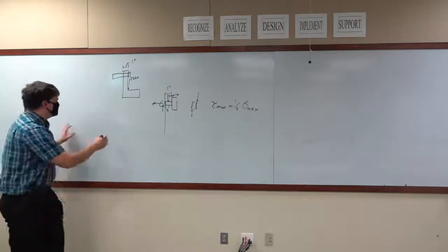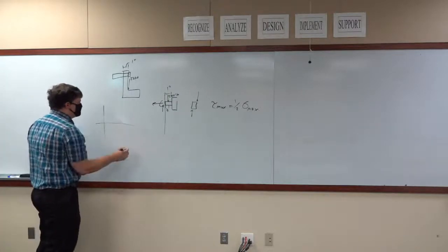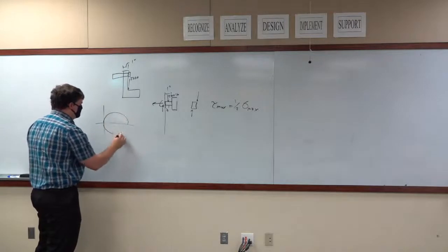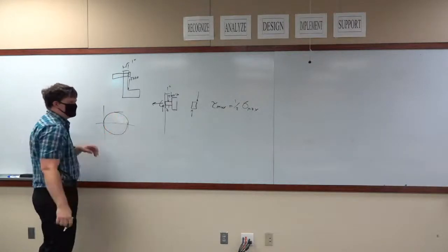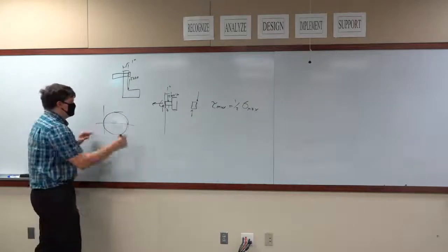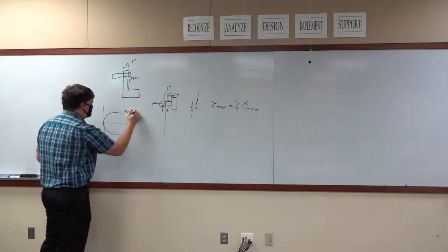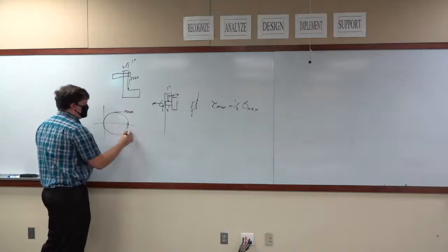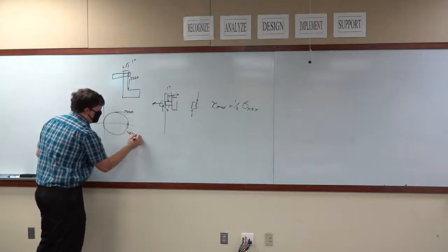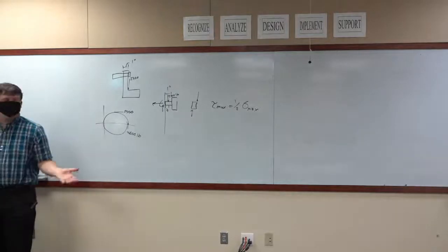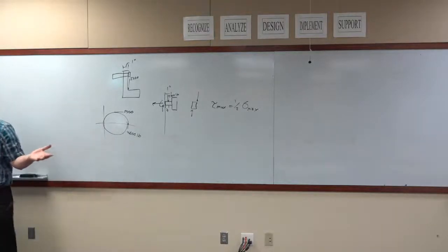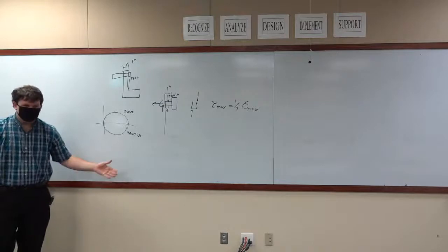If you look at Mohr's circle, if I were to draw out Mohr's circle here, okay, if here is the shear strength that we're applying to it, 2,300 pounds, then this tensile strength here would actually end up being 4,600 pounds in tension. Okay, twice the value.